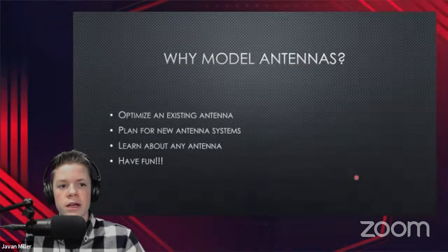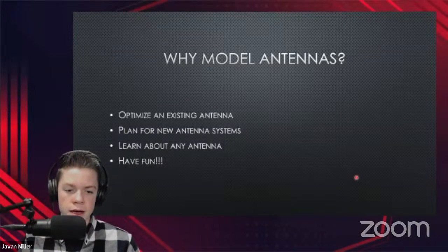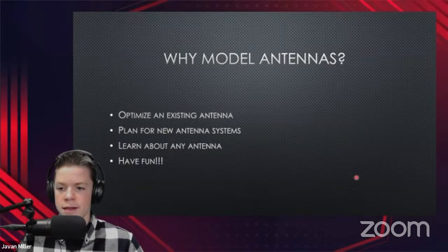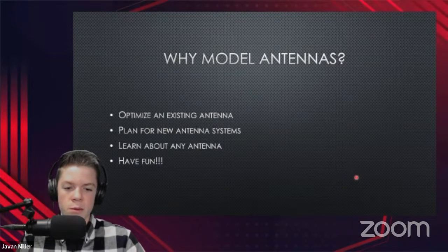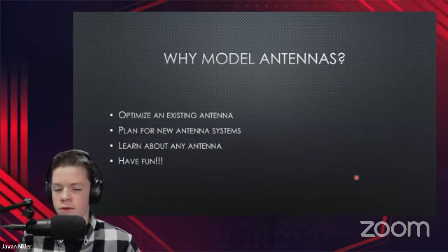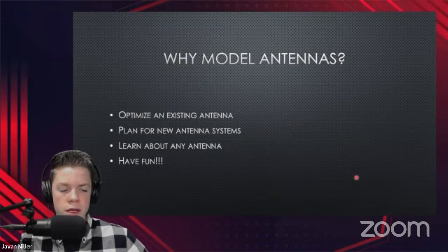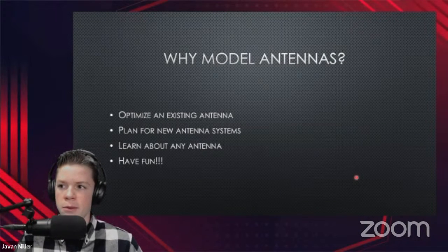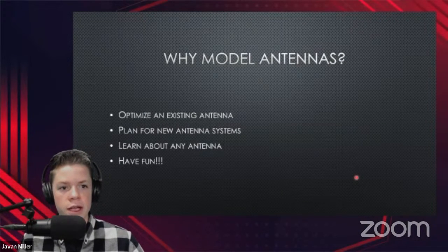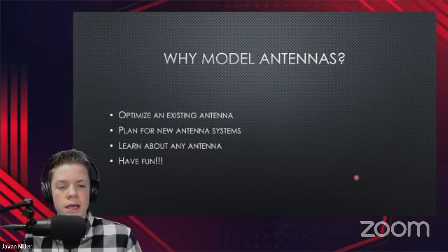And then also if you want to plan for a new antenna system, for instance, if I have, say, a dipole, a compromised antenna that's maybe only 5 meters off the ground and not at an optimal height for 40 meters, and I want to compare that to a vertical, because verticals might inherently have a low elevation angle for the radiation, but a dipole might have more gain because of the ground reflection. So you can plan for new antenna systems like that and just compare them,